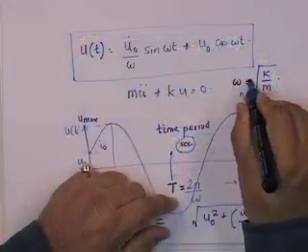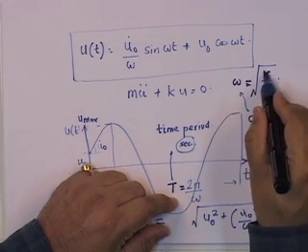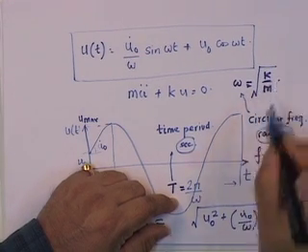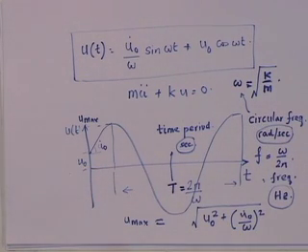So, T is defined in seconds, the circular frequency in radians per second, and f is given in hertz. Now, one important point over here is that omega, which is strictly the circular frequency, is also known as a frequency. In other words, omega and f are both frequencies. Omega is the frequency given in radians per second, and f is the frequency given in hertz, and T is the time period of the structure. Now, these are dynamic characteristics of the structure, and note that this frequency is related to the square root of the stiffness upon the mass of the structure.